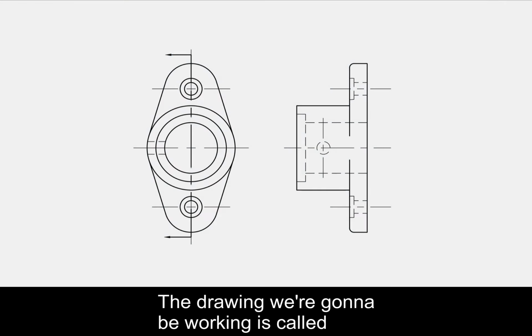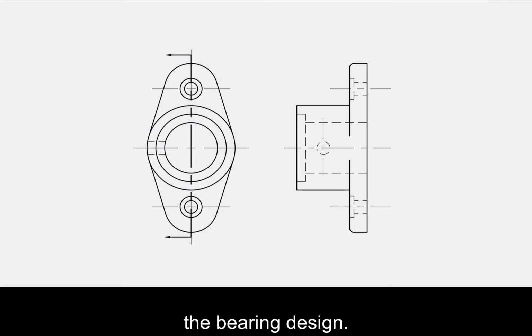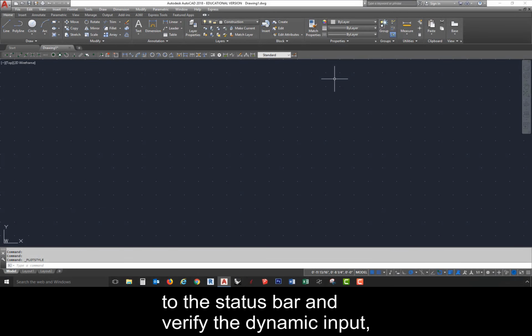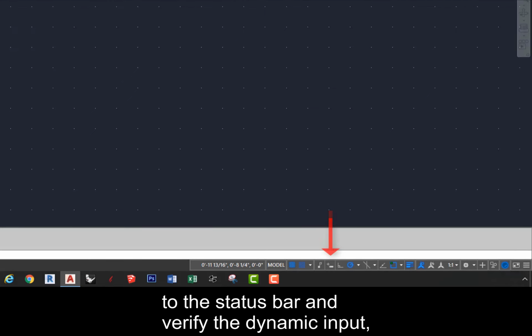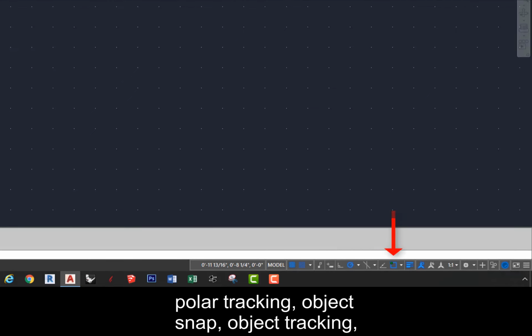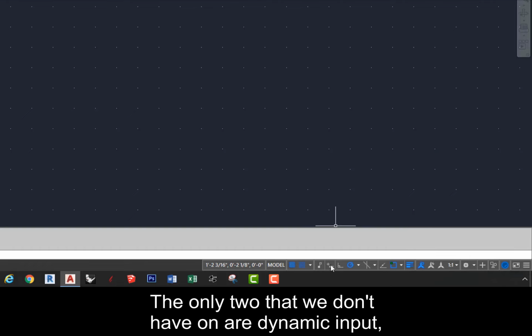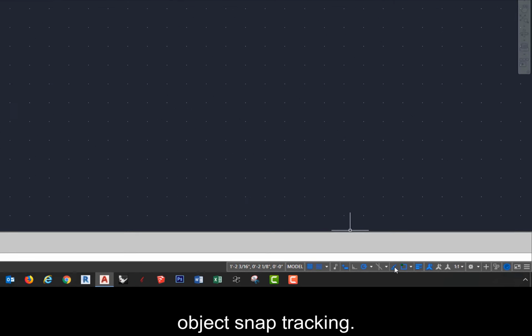The drawing we're going to be working on is called the bearing design. Before we get started with it, we need to go down to the status bar and verify that dynamic input, polar tracking, object snap, object tracking, and line weight displays are all on. The only two that we don't have on are dynamic input and object snap tracking.